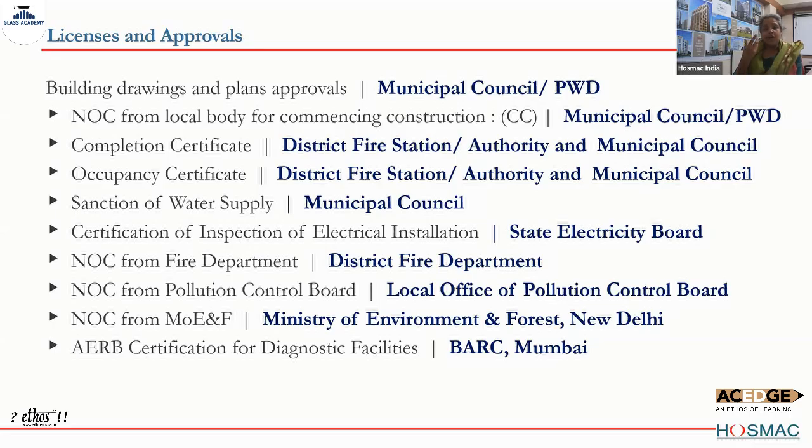So there is a very long list of clearances which you need for this building to stand on the plot that we have received. State-wise, these are different. So we need to talk to the local municipal architect to get these permissions in. And once we do get these, then there is a commencement certificate. That is when you can really start construction.